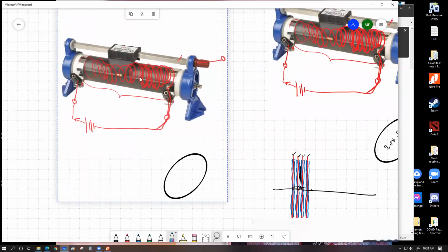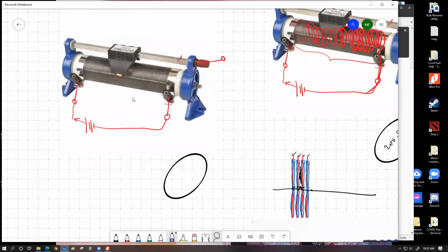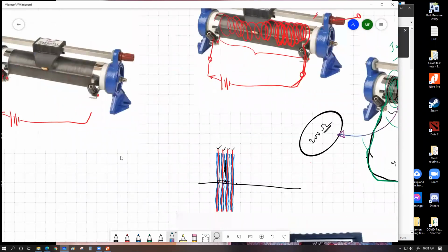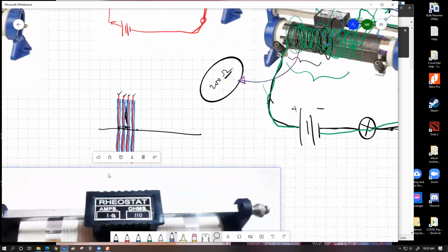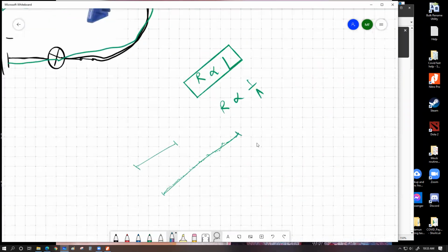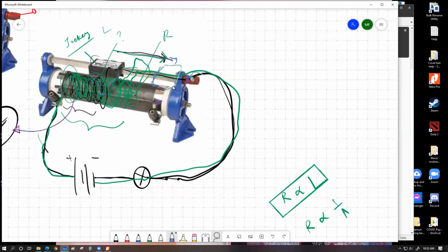Where the rheostat is situated, the rod. A second. This rod is usually made from brass, or it can also be made from basic cast iron with a little bit of nickel plating. It is a pretty thick rod in terms of metal, and you can see over here the resistance was also inversely proportional to cross-section area. So whenever we have a pretty thick rod, this can offer very little resistance. I mean, it has enough electrons to allow a very large amount of current flow.